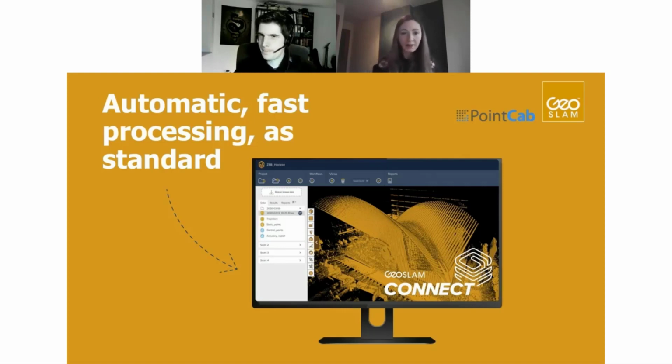Data is in .geoslam format, and Connect's got a preset of workflows where you can specify what output you would like to get from the data, what filtering you'd like to use, spatial decimation, and others like change detection. So once you set your data into a project for processing, it will run step by step through point cloud processing to get into the desired output that you specified, meaning that you don't have to wait for one process to finish and set up another.